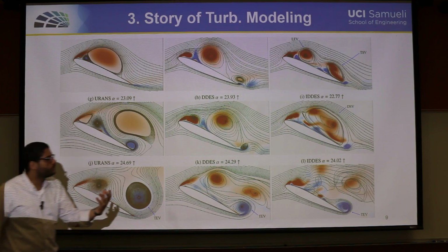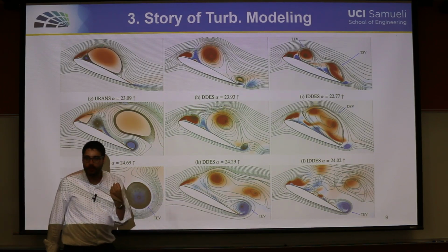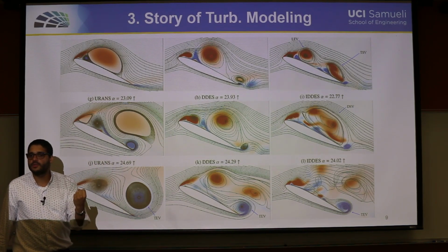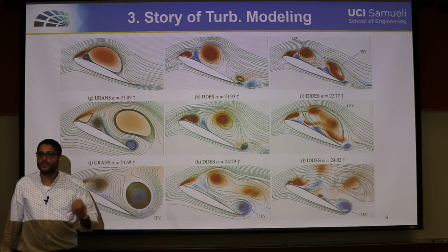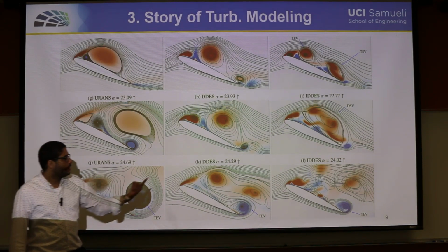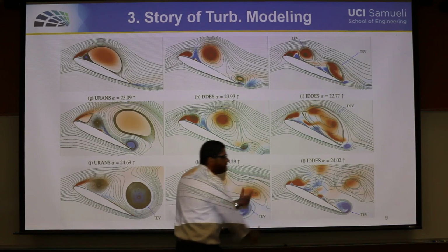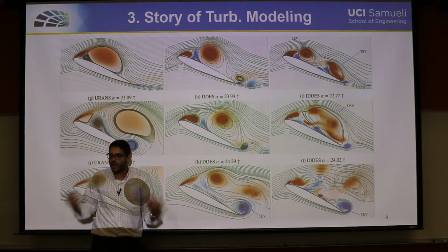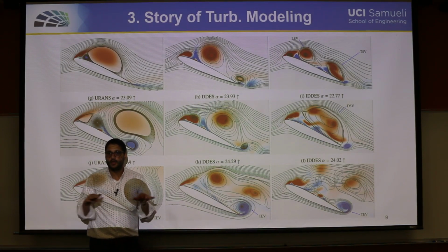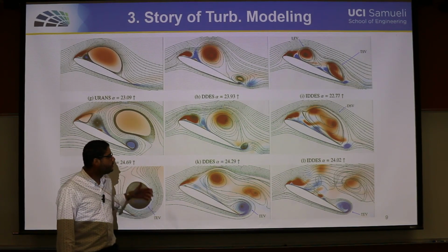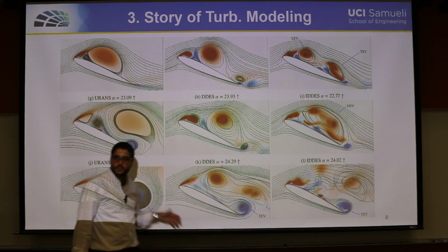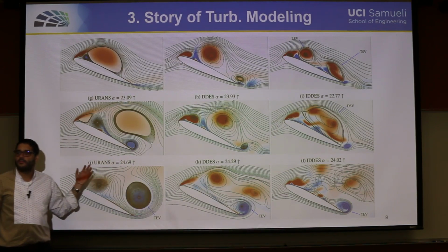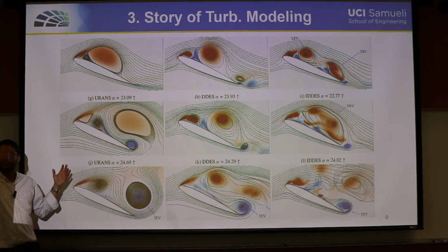And that's why I was trying to highly stress that doing a CFD simulation can sometimes be very expensive, because these two simulations must be done in a 3D fashion. You cannot do it in 2D. Even if you tried, you will not get a good result. A 3D simulation could be considered as 25 or 45 multiples of your 2D simulation.